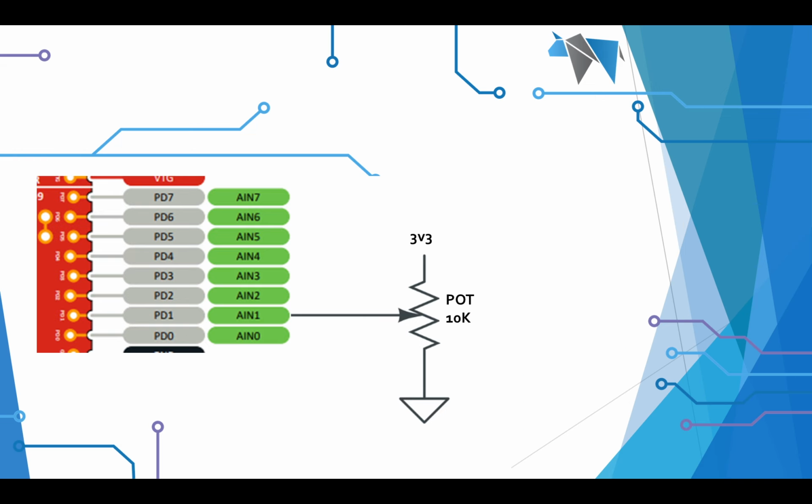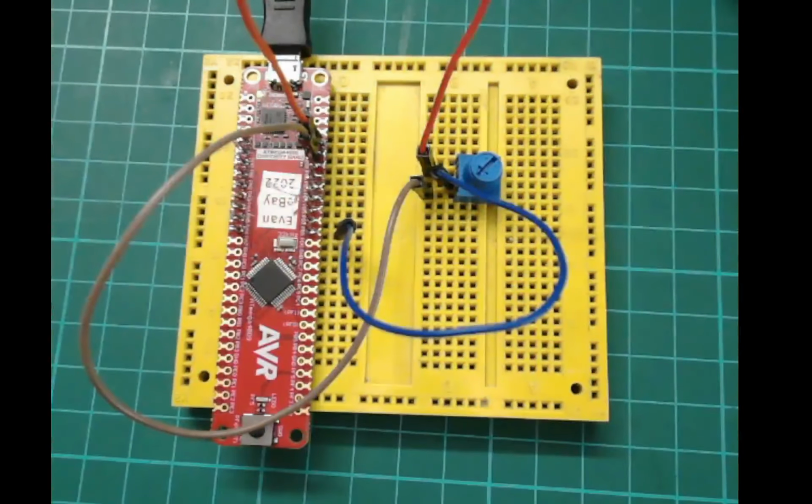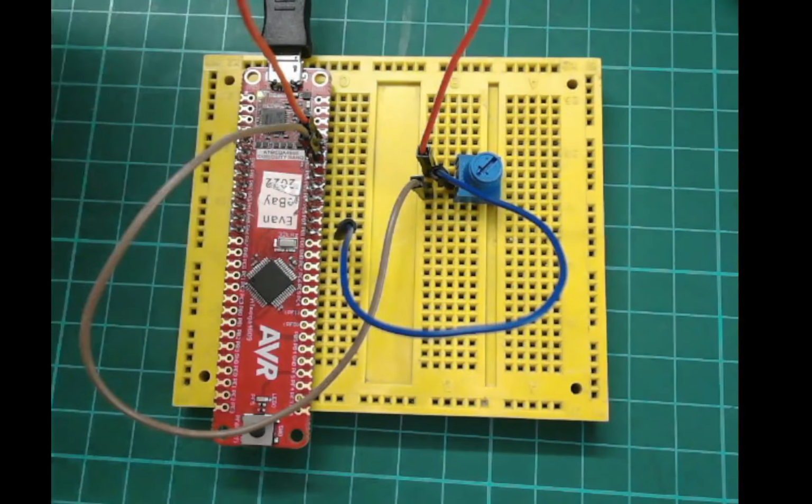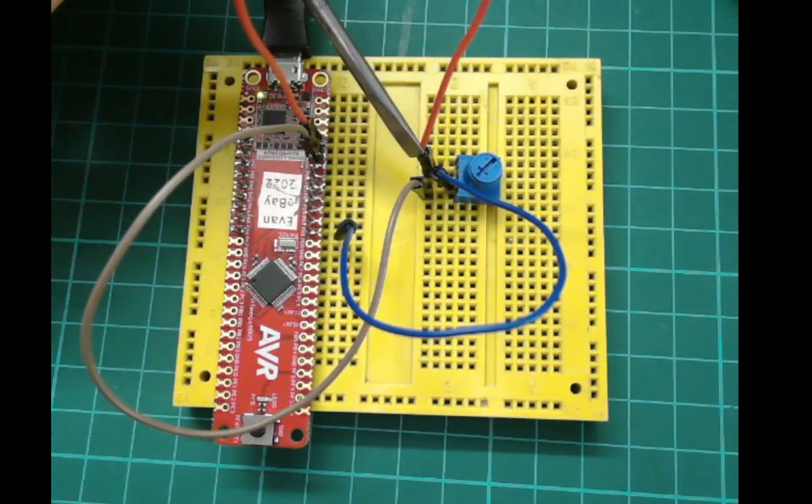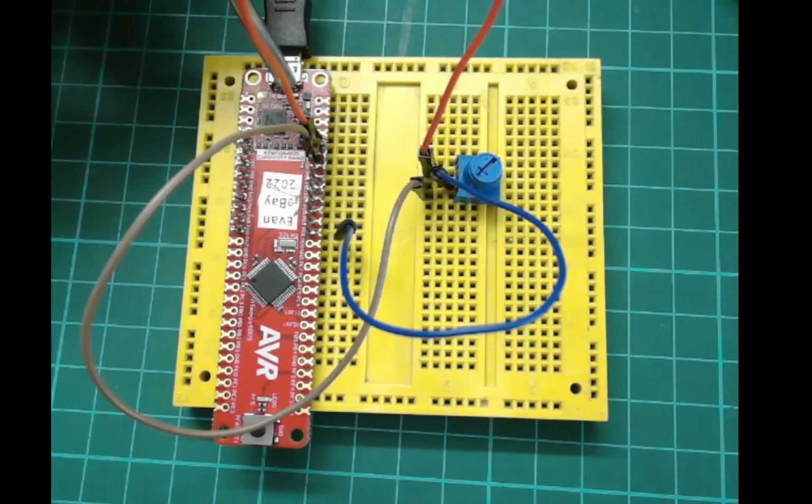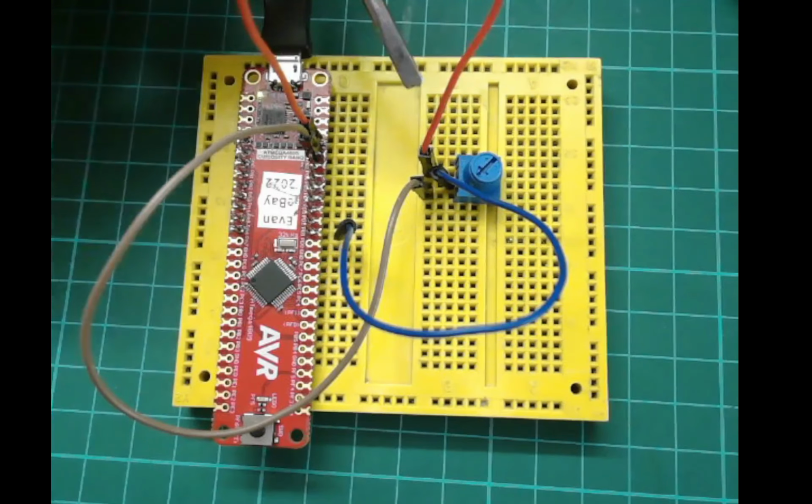So what I've got attached today is a potentiometer to AIN1, and I've got it connected to a 3-volt supply, with the middle pin on the potentiometer, the brush, and then we go down to ground, and we can see that on the camera. What we've got here, I'm taking a red wire to one side of the potentiometer from the 3-volt supply on this board, 3.3.